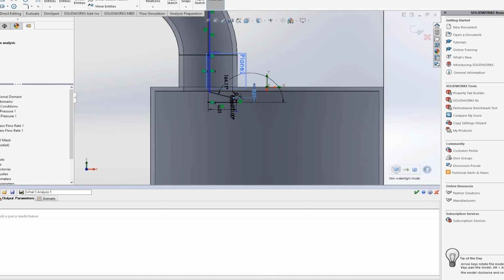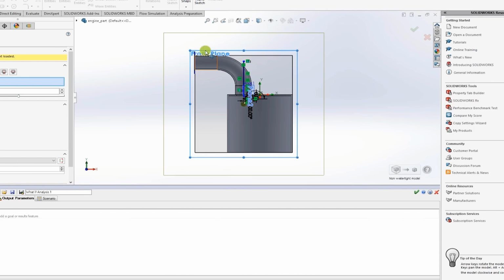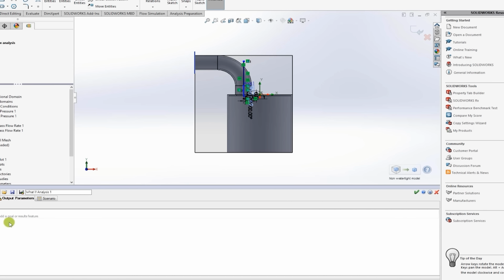So I'm just going to have this cut plane here. Let me just delete it and redo it so that you get an idea of how I did that. Let's just delete it and click on cut plane, and then click on insert. So when you do that, it's basically going to ask which plane you're going to use. So we are basically cutting the geometry using the front plane, which is perfectly fine. And I'm going to be, say, looking at the velocity. Oops, not the vorticity, but the velocity right there. And let's just click OK. And this is one of the things that I want.